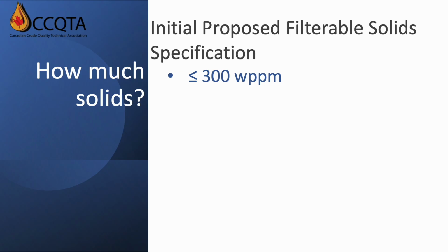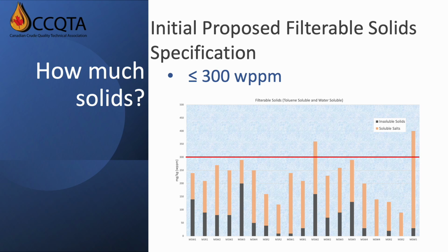solids was water-soluble salts. This chart shows the mixed sweet and sour filterable solids data with and without the water-soluble salts. The gray bars are the insoluble solids, while the orange bars are the water-soluble salts. In only 2 cases did the total filterable solids exceed 300 weight ppm, and with the soluble salts removed, none of the samples were even close to the initially proposed 300 weight ppm limit.